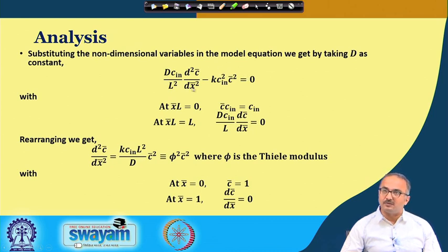After you obtain this equation, it is now simply a matter of mathematical manipulation to get the non-dimensional form of the mass balance equation. And please remember that when you non-dimensionalize, you not only non-dimensionalize the balance equation, you also non-dimensionalize the boundary conditions and initial conditions as the case may be. So, here also we are putting the dimensional form of the boundary conditions in terms of the non-dimensional numbers. So, here we obtain this non-dimensional form of the boundary conditions.